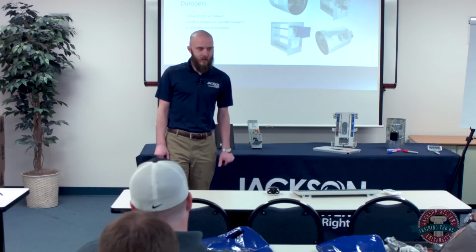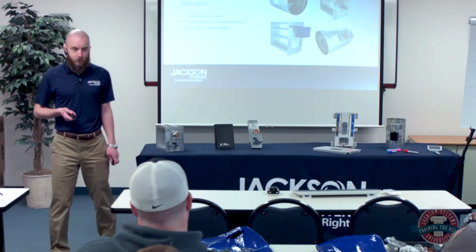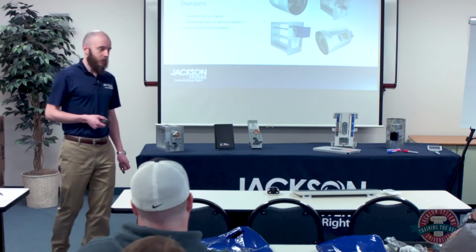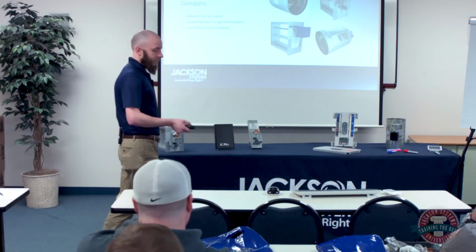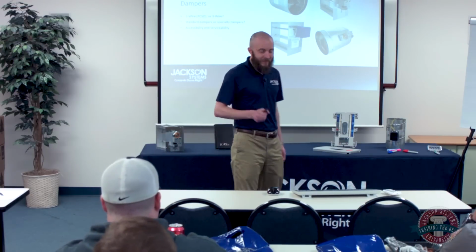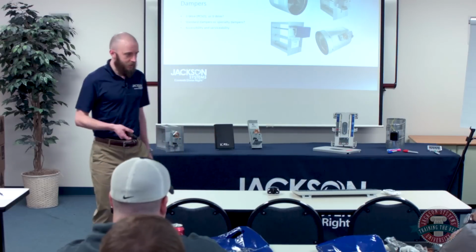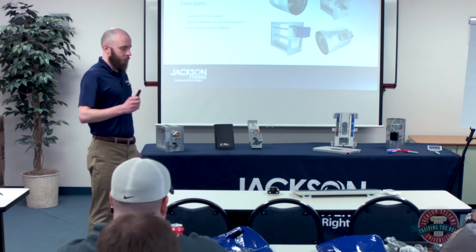One other major factor for dampers is to pay attention to the VA rating on the dampers. Different actuators are going to pull different amperages. So pay attention to how much current load you're putting on your system or on your transformer with those dampers.